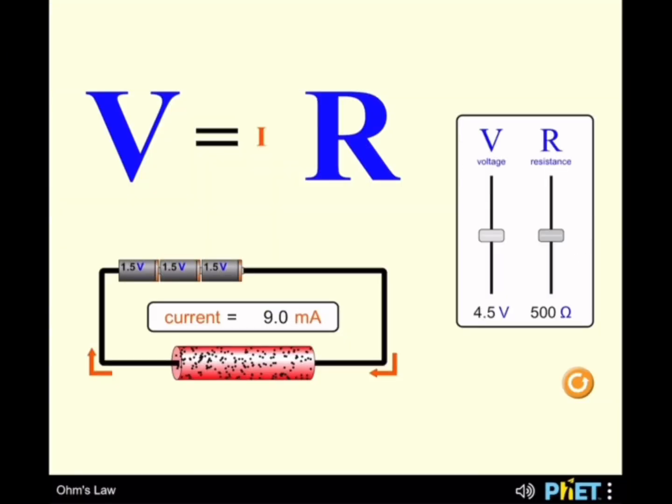And next would be Ohm's law. Ohm's law states that the voltage across a resistor is directly proportional to the current flowing through it, with resistance as the constant of proportionality. For example, if a resistor has a resistance of 5 ohms and the current is 3 amps, the voltage would be 15 volts. Ohm's law is crucial for designing circuits and ensuring they operate safely and efficiently.